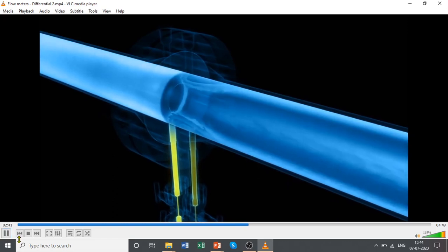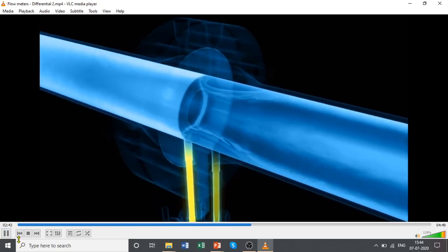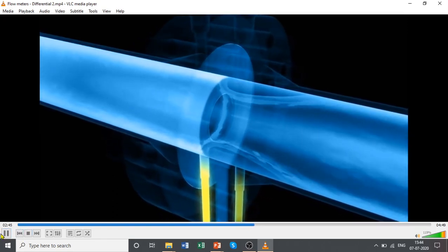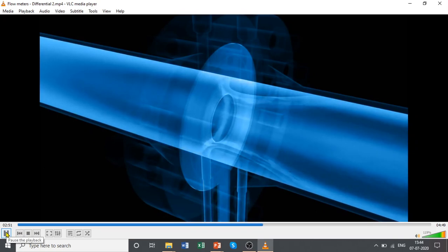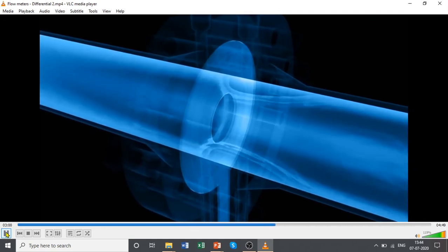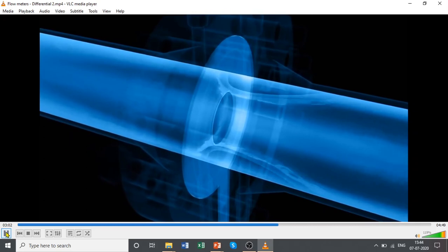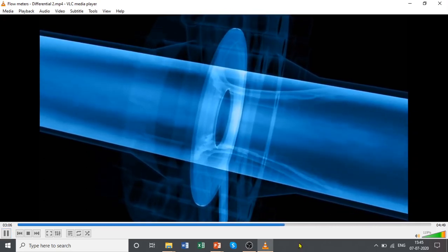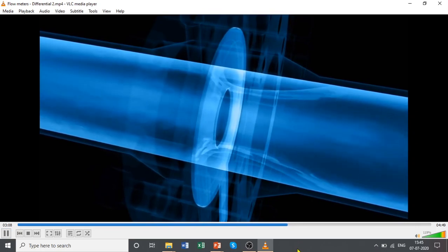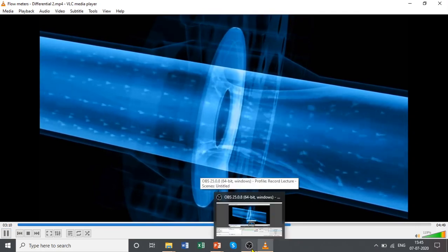The higher the flow velocity, and the resulting drop in pressure around the orifice plate, the greater the differential pressure measured. In numerous industrial applications, the orifice plate covers many needs of flow measurement technology. However, other designs are available for certain measuring tasks to minimize undesired effects, such as excessive pressure loss or abrasion of components due to solids carried in the fluid.